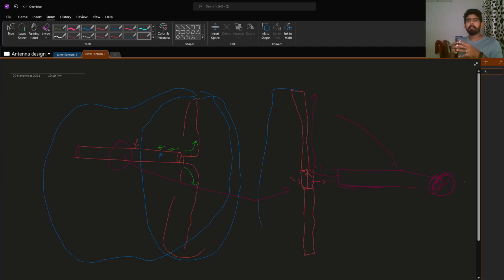The reason for the wave port is that if the frequency increases a lot, and the coaxial dimensions themselves become comparable to lambda, the coaxial cable itself contains more modes. At that time there is again a chance your simulation may be wrong. When you fabricate it after the simulation, the pattern is different from this. So this is just the theory I put.